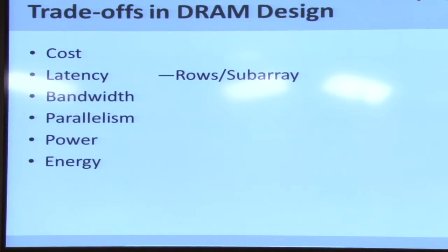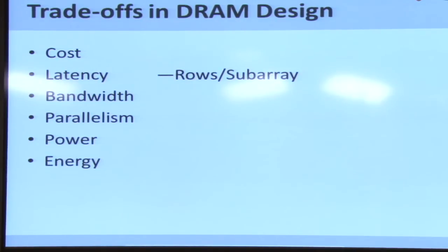To reduce the pin count of your command bus. That's a good one. So if I had to give a separate command to each chip every time, it means I would need 8 times the command bus bandwidth. Right? I need 8 times more pins for my command, and what?